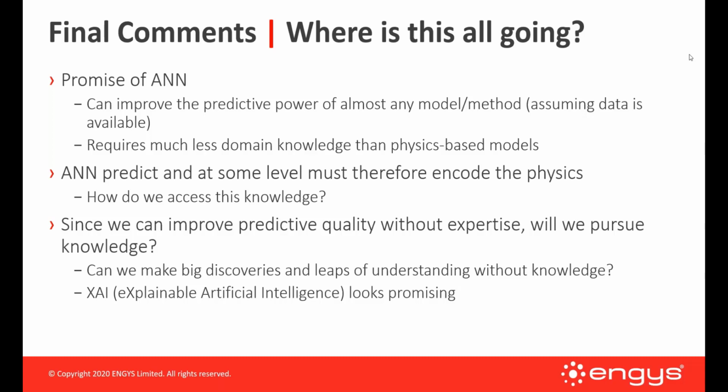In terms of the CFD, the case I showed was relatively coarse. The box was relatively coarse, so that is not really representative of the kind of cars that we would run. For RANS or DES, we basically make the same meshes these days. So that's 100 million, 150 million typically for a small sedan. It could be bigger for an SUV. So yeah, I hope that answers the question.